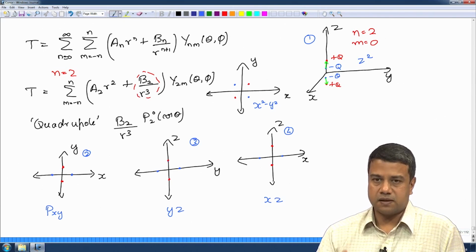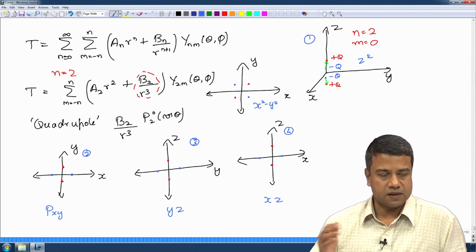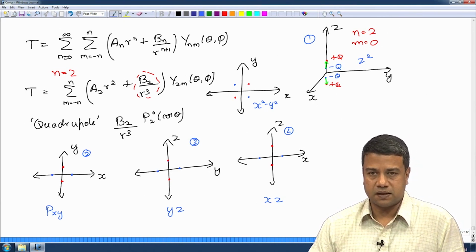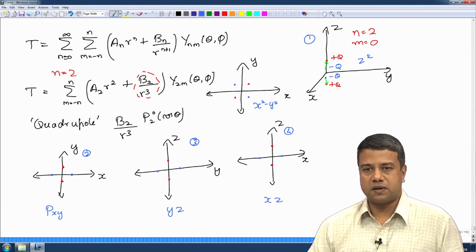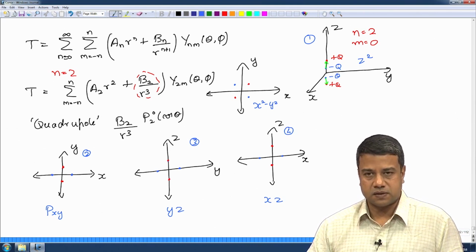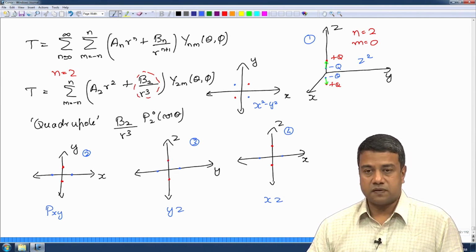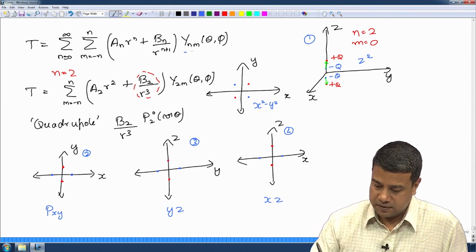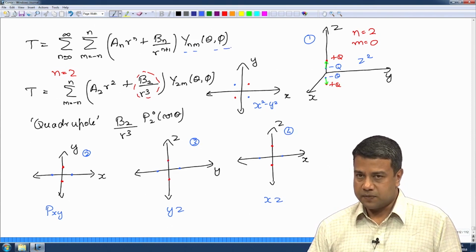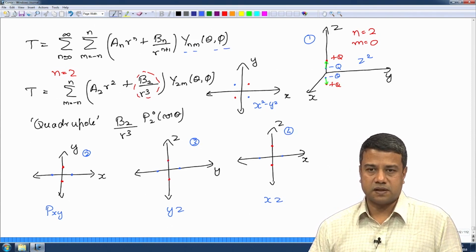These are identical to what we got by looking at the heat conduction equation with a delta function source. The two are identical. You can have a 1-to-1 correlation between the solutions for the delta functions, the sources and sinks, and the Legendre polynomial expansions. Since all of these are orthogonal to each other, any temperature field due to any source can be expressed as a linear combination of these.